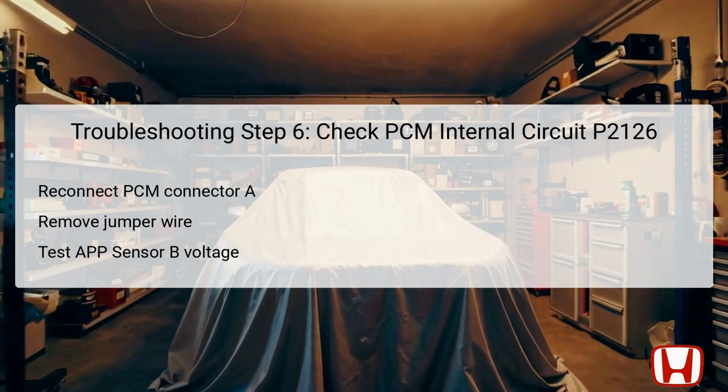If they do, this indicates a continuing fault, suggesting either the need for further consultation of service information or the substitution of a known good PCM for analysis. Conversely, if successful readings are obtained, replacing the accelerator pedal module is warranted.